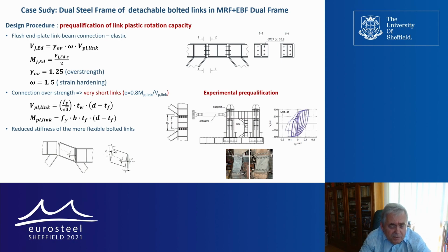In principle, we must have a pre-qualification of the links in order to confirm the capacity of plastic deformation which can be developed by such detachable link. Of course, if you have, let's say, a previous test, we can simulate numerically the behavior of the link using validated numerical models.